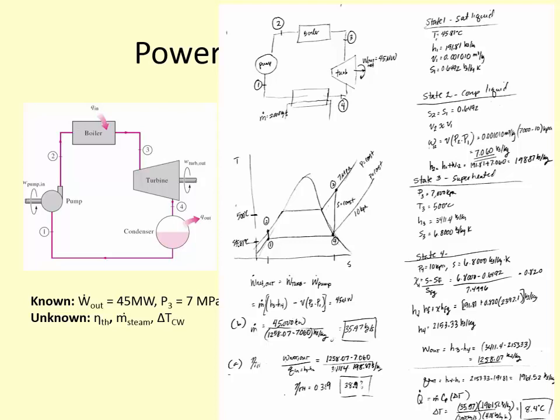So we also have cooling water. We know the mass flow rate of the cooling water. So Q in to the cooling water, this is different than the Q in to the boiler, is going to be equal to C sub P times T2 minus, well, no. I'm not going to use 2 and 1 because that's confusing. Temperature out minus temperature in of the cooling water.